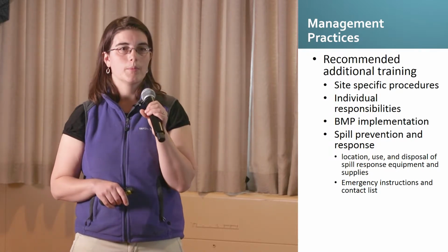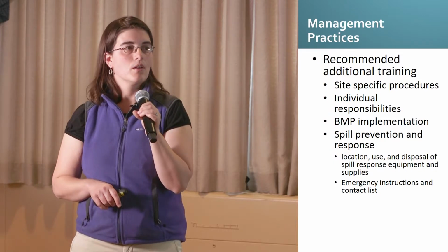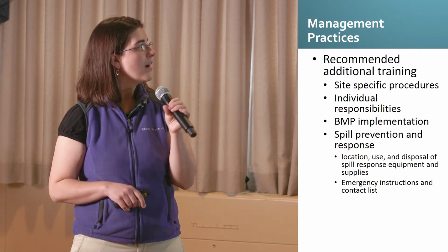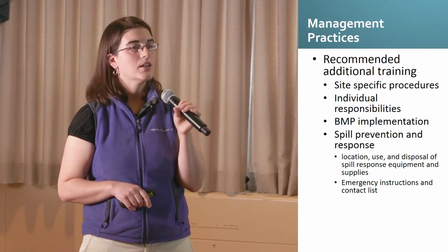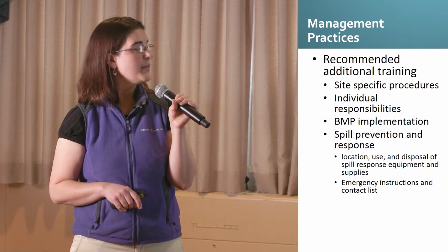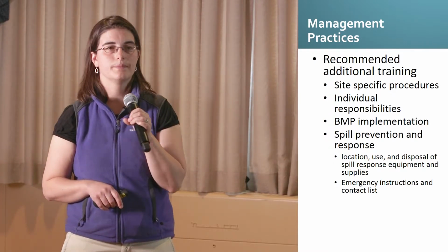And then BMP implementation, the specifics on what type of BMPs are proposed for different areas, for different activities. And then the spill prevention and response, specifically on the location, use, and disposal of spill response equipment and supplies, and the emergency procedures and the contact list.